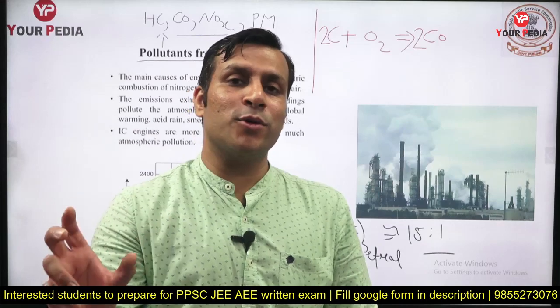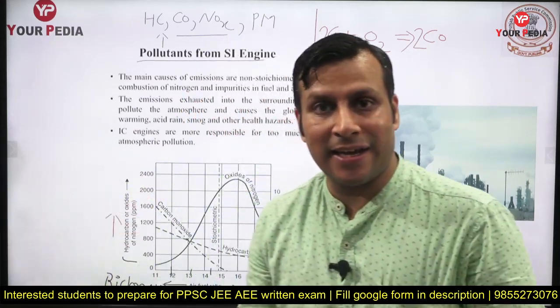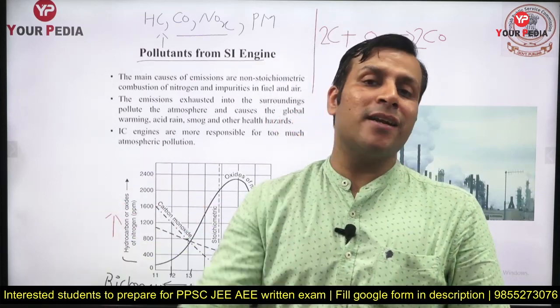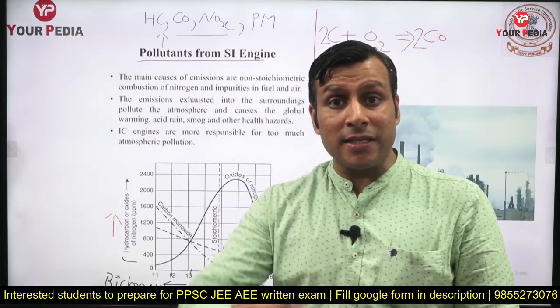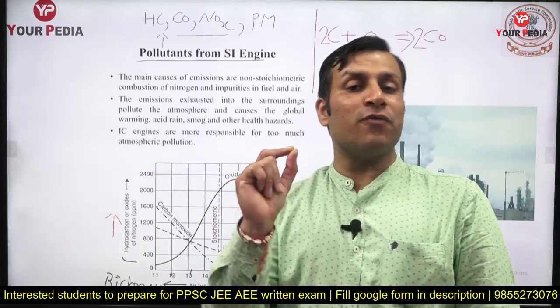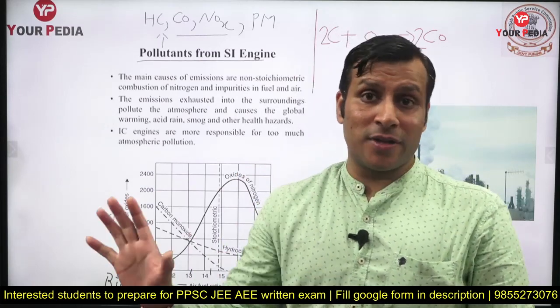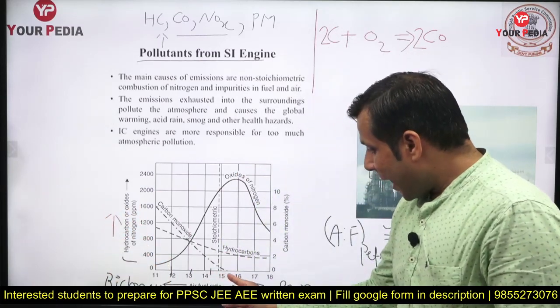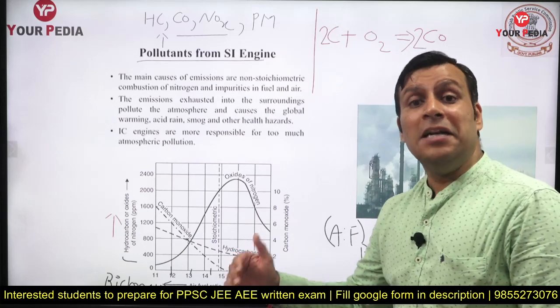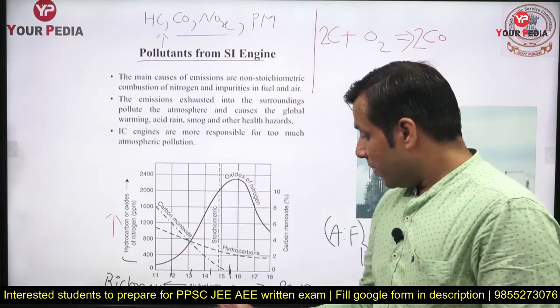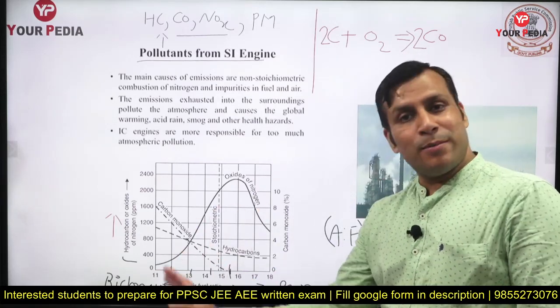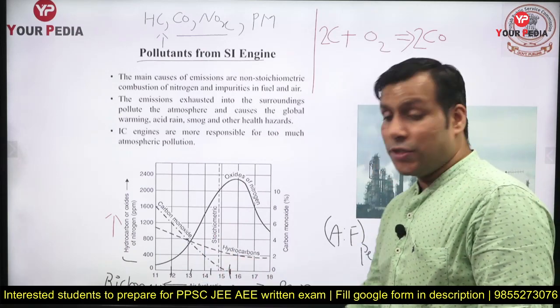Obviously some carbon monoxide emission will be there, because each and every fuel particle is not going to get that air. But if you pump some additional air inside the engine, there are chances that every fuel particle will get sufficient air to carry out complete combustion. So that's why at a slightly lean mixture, the carbon monoxide emission will reach the zero value.